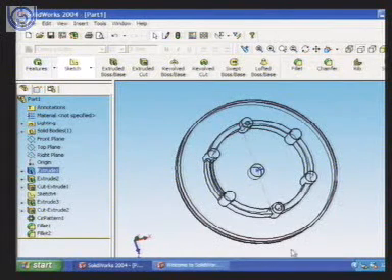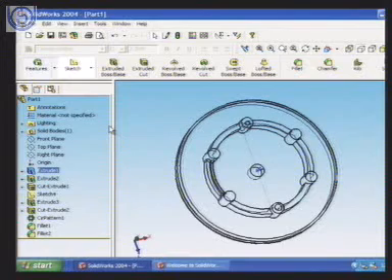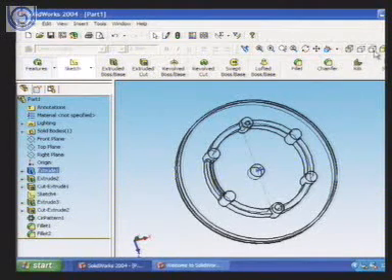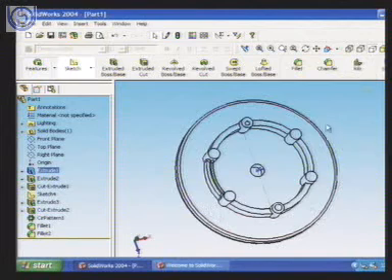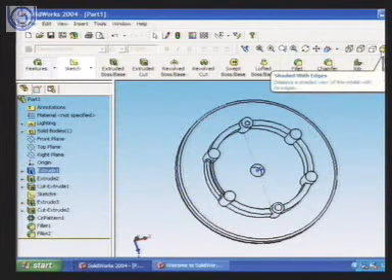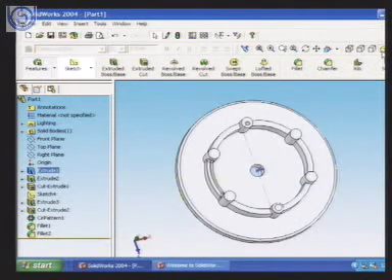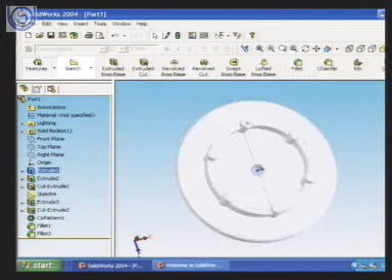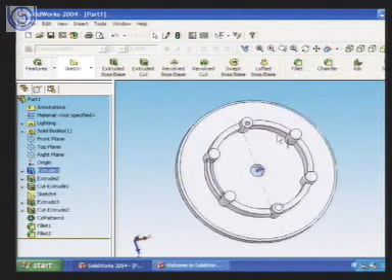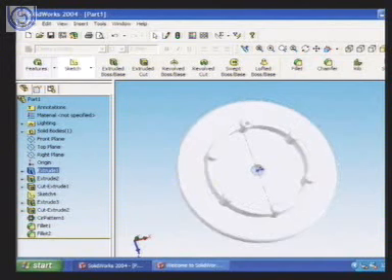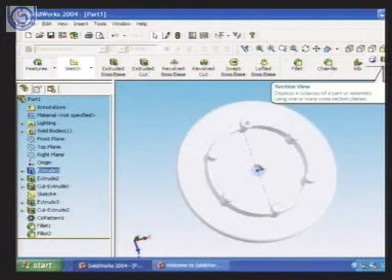If we say hidden line visible, you must have read in your chapter number 3, visual realism, why we have to remove the hidden lines. In your Computer Aided Design chapter number 3, why it is required to remove the hidden lines. You can see how the model becomes ambiguous. The moment we remove the hidden lines, it becomes more clear. Then we have shaded with edges. Then we have shaded. So this is the difference. Here only the edges are shaded. Here everything is shaded. Then you have the cut section.